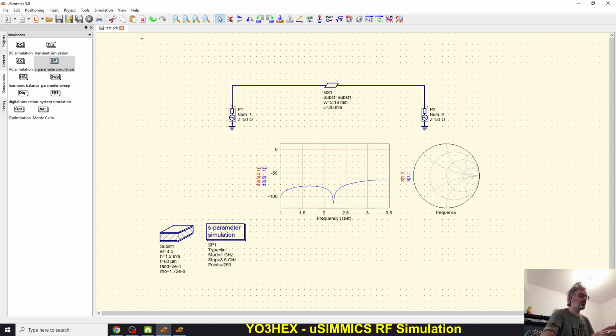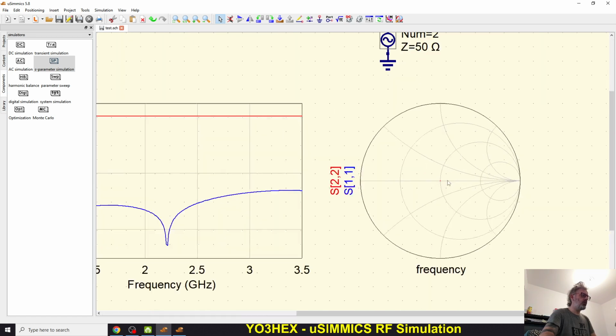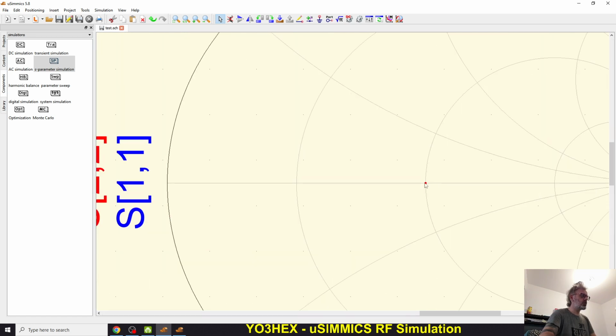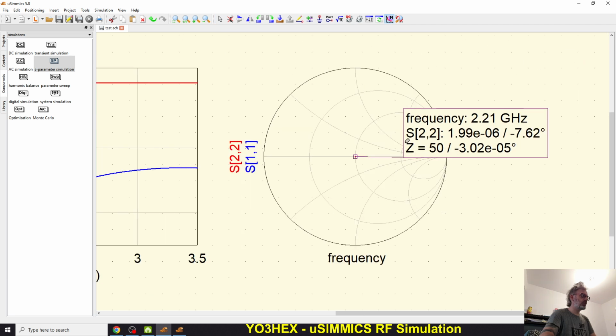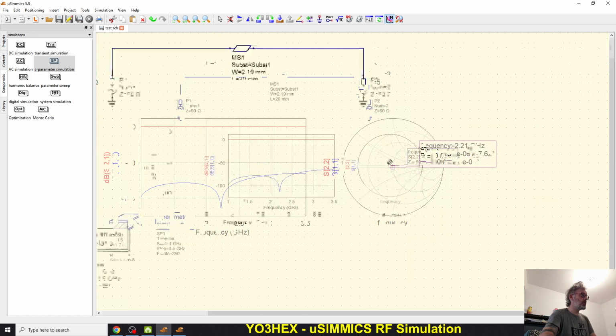So 4.5, between 4.2 to 4.6, I've seen a lot of values. I didn't measure it for what I have. Those are kind of the numbers that we are in. So this is almost a perfect match. We are spot on in the Smith chart here, and that will allow you to see 50 ohm, dead on, which is good.